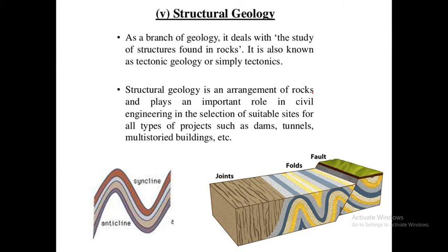Then, structural geology is the arrangement of rocks and plays an important role in civil engineering in the selection of suitable sites for all types of projects. Yeah. The next is how this is practically implemented. So all this concept can be put to practical use. Practical working is more prominent in the civil engineering field, because various constructions of dams, tunnels, buildings, everything, this should be kept in mind. If it is highly structured or if it is a highly folded terrain, you should have to rethink various construction, because we can call the area a tectonically active region.